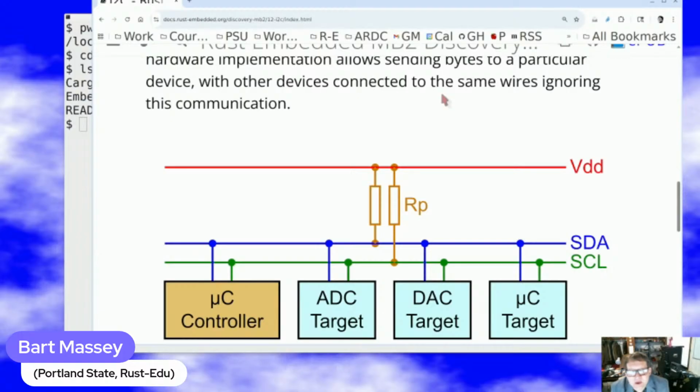Sometimes it's simple. Asynchronous serial over those wires makes sense a lot of times. You can make it go reasonably fast, but not scary fast, because the UART itself has trouble when the bits are too close together deciding when to look for changes in the bit pattern.